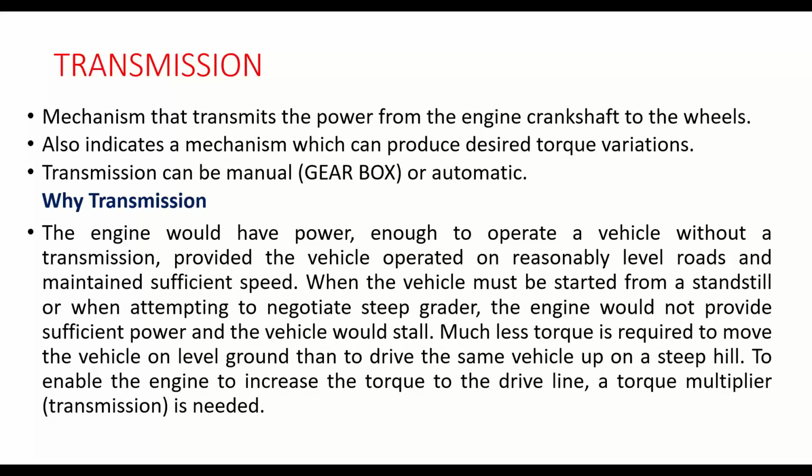Engine keeps on giving you the power. The gearbox, what does it do? It will rotate the shaft in the reverse direction, so your wheels start moving in the reverse direction, so that you can take your vehicle back. Correct. So these are the reasons why you need a transmission system. Even though the engine is the heart which produces torque, that torque cannot be equally used under all considerations. You need to vary the torque depending on your requirements, load, the direction of movement, forward, backward, etc. So in order to accommodate that, we need a transmission system.